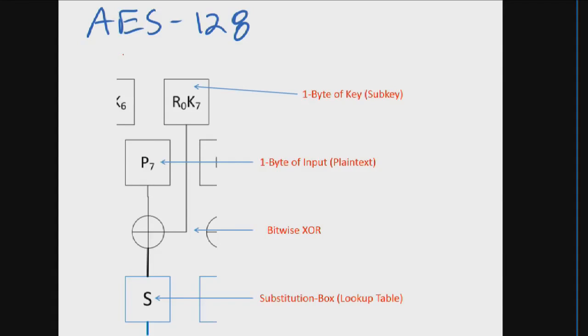What this means is that with this differential power analysis, we no longer care that it's 128 bits, or if it's AES 256. It doesn't matter, because we're breaking it 8 bits at a time. And that guess and check, it's only 256 guesses, and it just scales linearly with however many bytes we have. We no longer have this crazy growth in the search space. So you can break it, and I'll show you on a laptop in sort of a few seconds type thing.